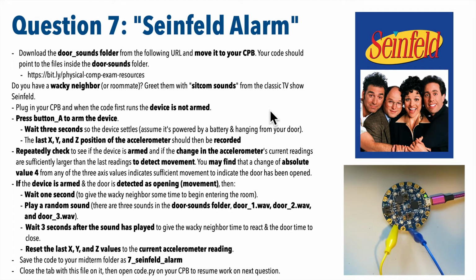So the setup for this is, again, if you have a wacky neighbor or a roommate, it'll play the sitcom sounds whenever the door opens and someone walks into the room. So you want to plug in your CPB, and at first the device is not armed, so it's not going to go off. But when you press button A, then you arm the device.